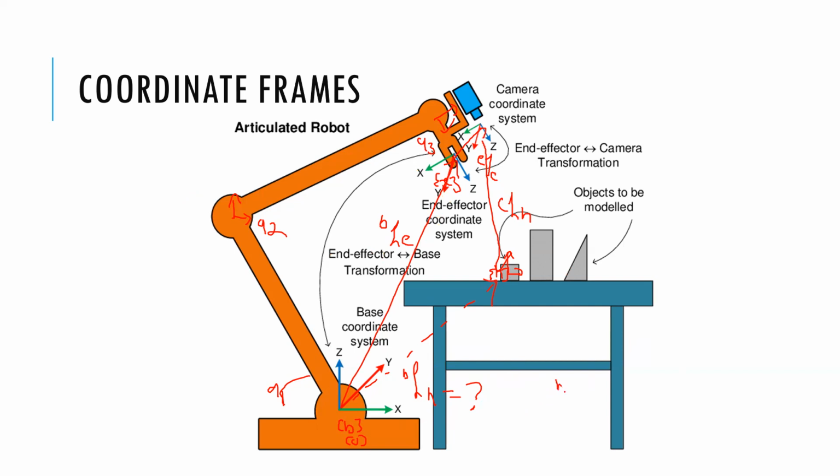Where's the object to end effector here? I notice you're going backwards here, but you could also go through multiple other chain loops here. So you could be writing this as a positive, and you can also figure out negative things, depending on which direction you're going. And these are going to be a homogeneous matrix, which is also represented by T in a lot of places, which is a 4x4 matrix. And we can also invert these matrices here to go to the other side. So that's if we wanted to go this way here.